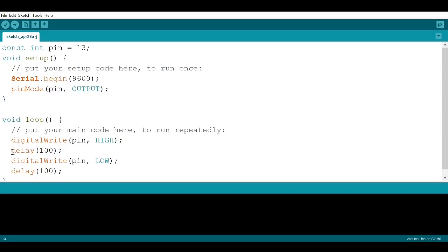So why have I given these delay values is that if in case I do comment them, what's going to happen is your LED will blink so fast that it won't be perceivable to your eyes, and you'll end up just viewing a dimmer shade of the LED's high output. So for us to perceive it, we are going to leave it uncommented.